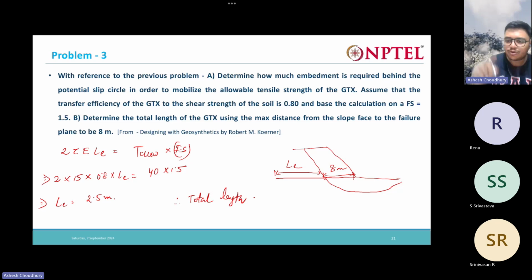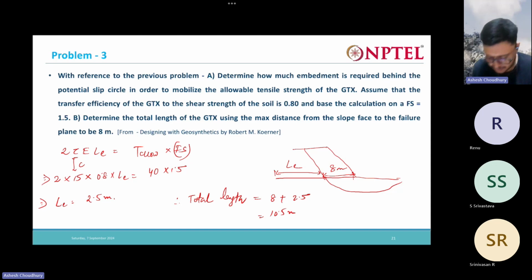Here, understood, right? Here we don't have to use 2 times the normal force times tan phi, because it's a completely clay soil, so we are using the cohesion directly. In place of this, we are using the cohesion. But 0.5, done. Simple, right? Very simple.